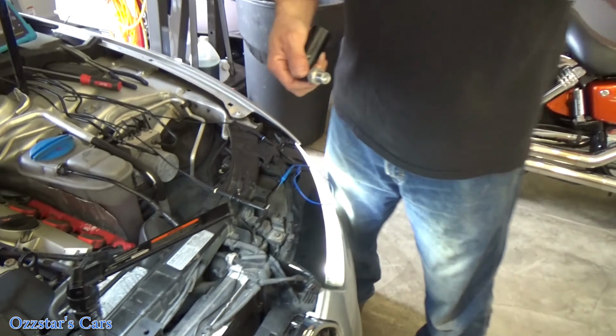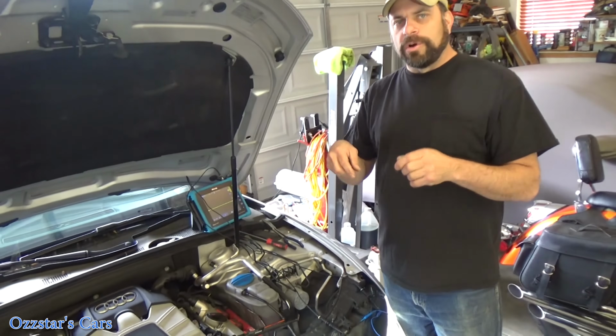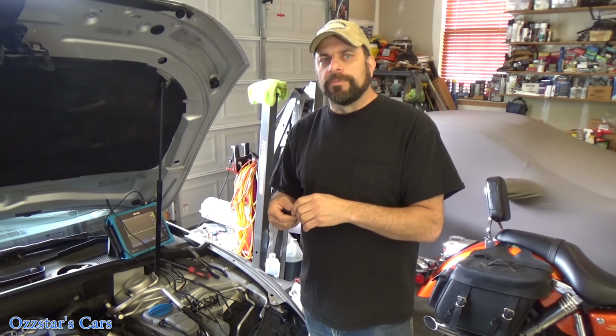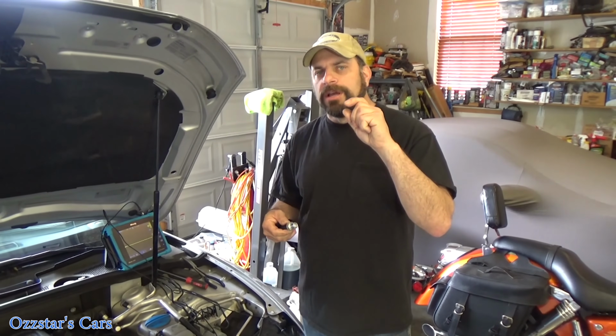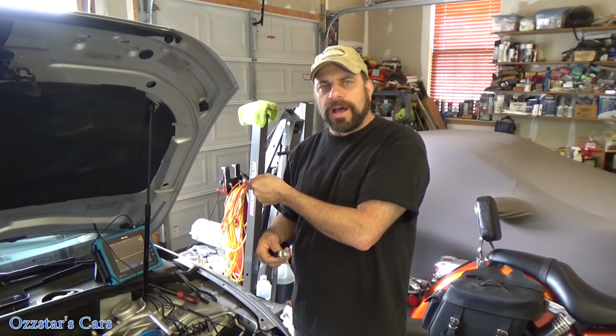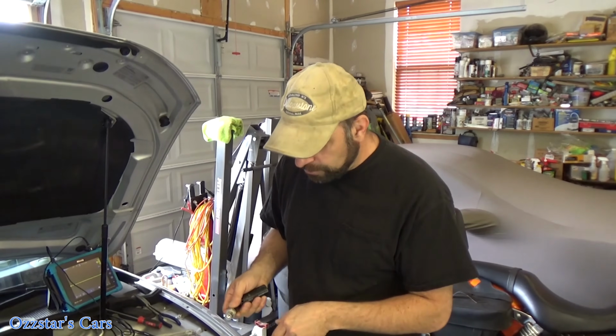The thing that you don't have to worry about is once you remove this, now on some models, not on these Audis, VWs, they have a Schrader valve in it. A Schrader valve is the same valve like when you put air in your tire at the valve stem. So as soon as you remove this, as long as the Schrader valve is working properly, boom, it will hold the refrigerant in for you. You don't have to worry about it, and they don't usually go bad.